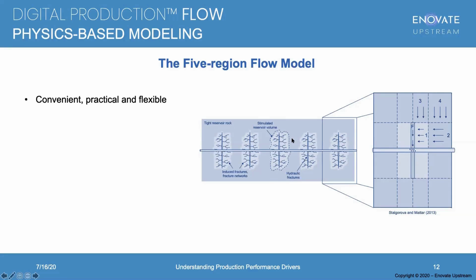We talked earlier about the complexity of having multiple stages with multiple properties, like what I showed you with the instantaneous shut-in pressure, remember? So what this model does is, we can assume that instead of having these distinct stages, we have equal stages with average properties, which makes the problem more tractable. Nonetheless, we can still simulate this model on a stage-by-stage basis, and that's exactly what we do in real time.